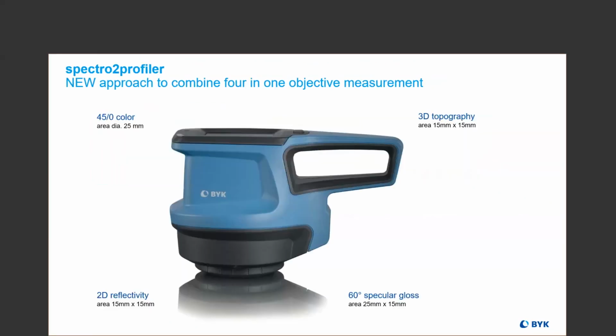So to sum up, our overall visual perception combines color, gloss, and surface topography. And so in order to fully and accurately evaluate and control for the look of a surface, we need to be able to quantify all of these things. And that's why this instrument comes with 45-0 color, 60-degree specular gloss, which are both traditional measurements, but also these new techniques, the 2D reflectivity and the 3D topography, specifically for quantifying the texture of the surface.